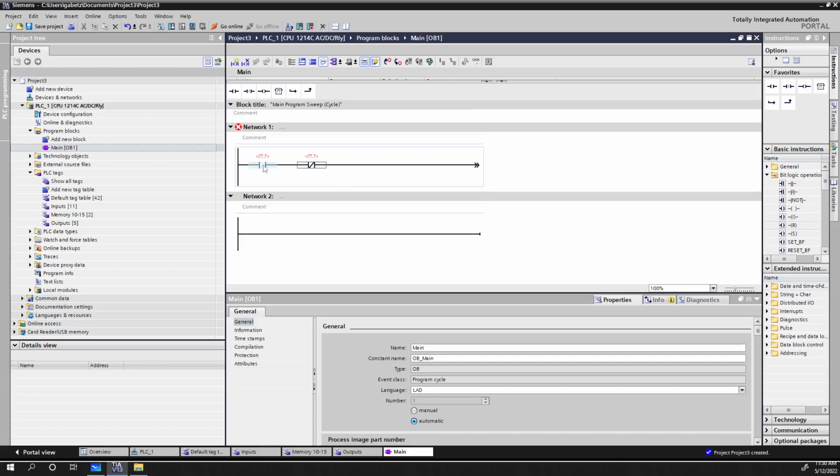So I have followed Big Bad Tech's YouTube channel, and I have started calling them make and breaks. This symbol, the normally open one, I personally call a make, and I call it that in every piece of software. Allen-Bradley, I believe, calls it examine if closed and examine if open, and it's like, that is too much of a mouthful. So I'm just going with make and breaks, and that's what I follow. So the one over here on the left, this is the make.